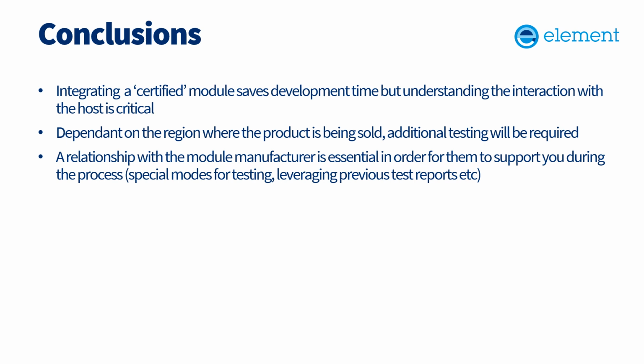And the relationship with the radio module manufacturer is essential in order for them to support you during the process. If there's special modes of operation that you need to put the radio in, for example, or leveraging previous test reports, data, all of those sorts of things is really critical to minimizing the requirements on you as the host equipment manufacturer. Having a clear strategy for compliance is essential.